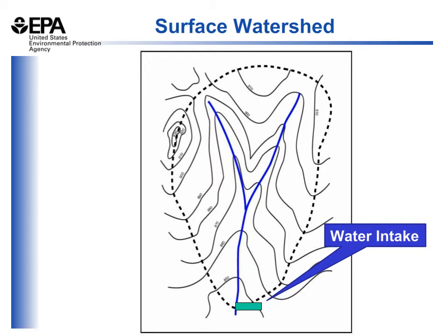If there's large livestock facilities within this area, you may be looking at manure runoff through the watershed coming into the drinking water supply and the nutrients and the pathogens that may be within that runoff. If there are significant road networks and you're in an area where road salts are applied to minimize snow and ice impacts in the winter months, we may be having sodium and chloride coming down into the drinking water supply. If there's a road network as well, you may have pathogens and hydrocarbons and heavy metals from the use of those roads that could be affecting drinking water quality as well.